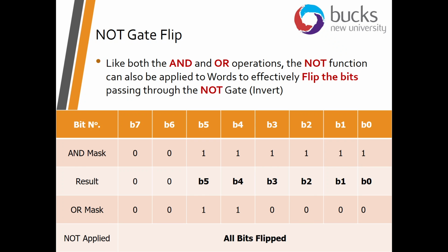Now where do we see flipping? Well, we saw flipping as a useful little mathematical trick to do our 2's complement. So we said flip the bits and add 1. So flipping the bits is actually an application of a logical process, with a NOT gate flipping those bits over and then adding 1 to it. So straight away you can see some potential there if you're building logic circuits which are going to carry out mathematical functions within a computer.